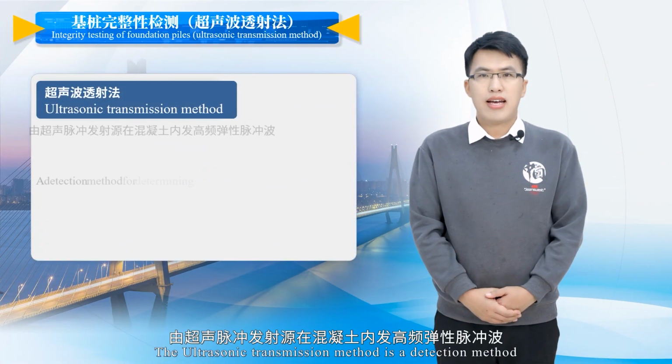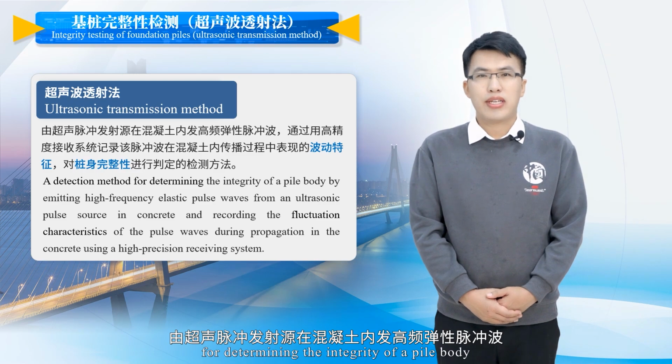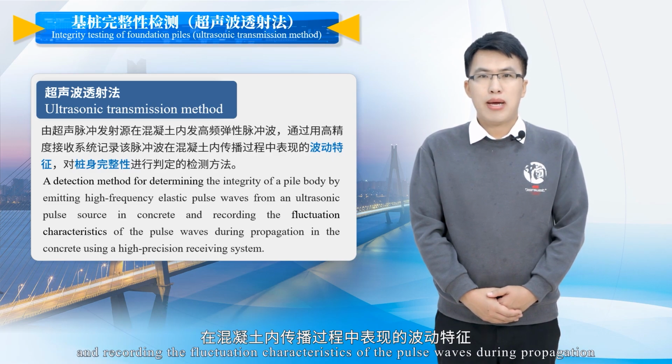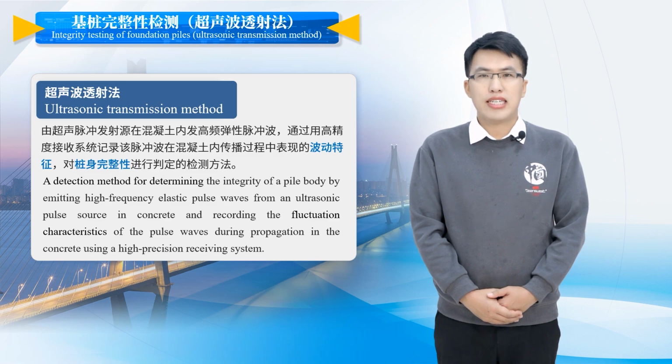The ultrasonic transmission method is a detection method for determining the integrity of a pile body by emitting high-frequency elastic pulse waves from an ultrasonic pulse source into concrete and recording the fluctuation characteristics of the pulse waves during propagation in the concrete using a high-precision receiving system.